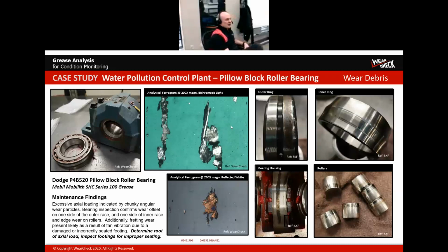So we had a conference with the customer, and my concern was that this inner bearing might just be cylindrical ball bearings in it. But it turns out that it was the proper bearing for it. They had tapered bearings, and it was bidirectional tapered bearings. So by all means, it was the sort of bearing you would expect. Yet they were still getting abnormal axial load.